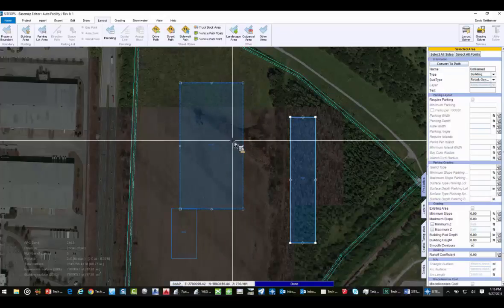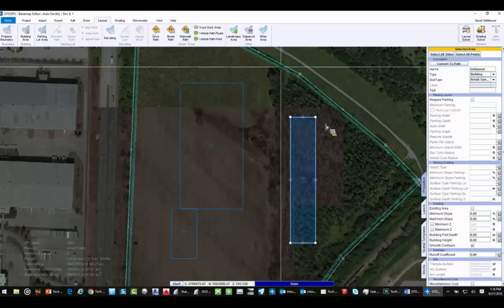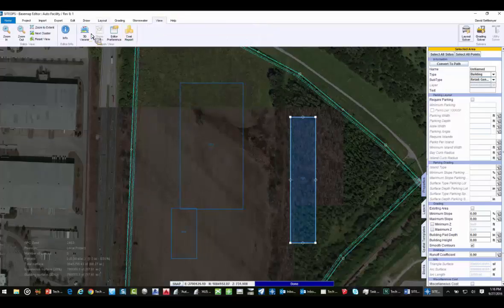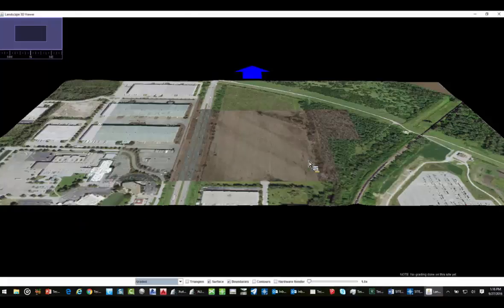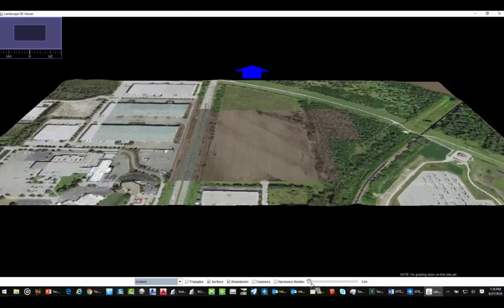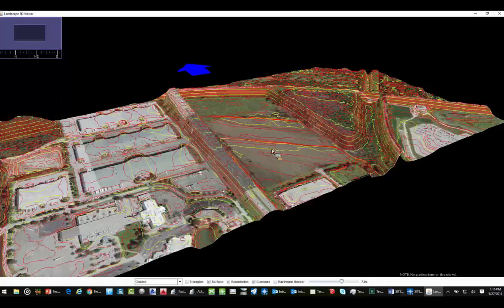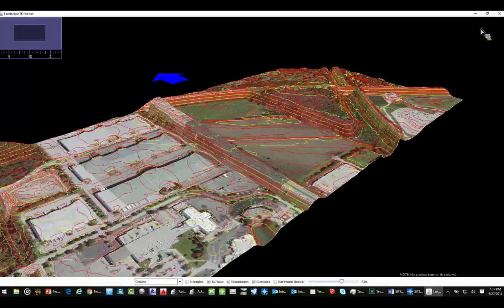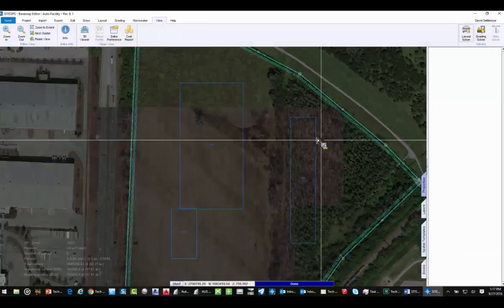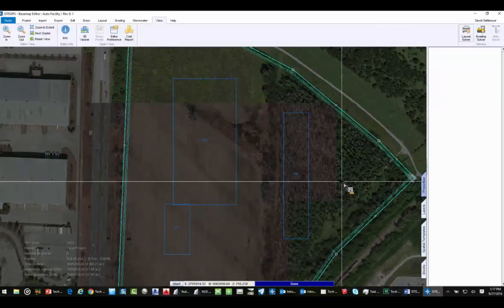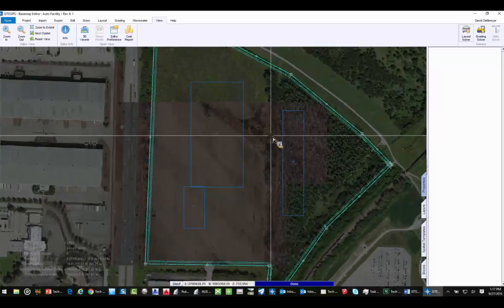All right, so we go in again. You've got 3 buildings. Now, the one thing you're going to do inside of SITEOPS is we're going to work in a 3D model, even though we're going to keep it as simple as a 2D model. So if I come in and look, we've got a little bit of a low area for this plateau type flat area. We've got a little hill over here to the right, so we definitely can see where we're going to get some dirt, assuming that it's good. You can put in your geotech information, so if this was bad soil, rock, something like that, SITEOPS can handle that. So let's just do something really quick just for what we're doing.